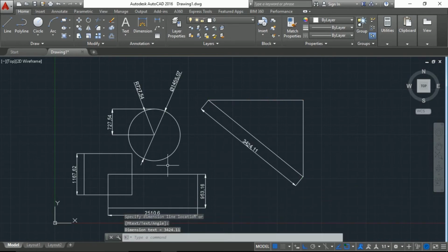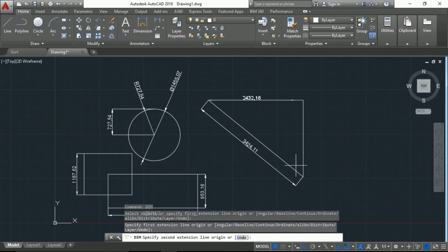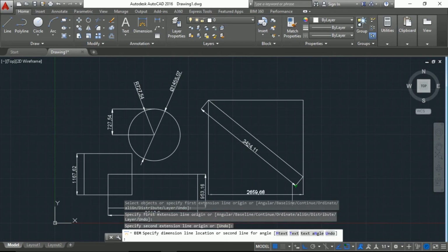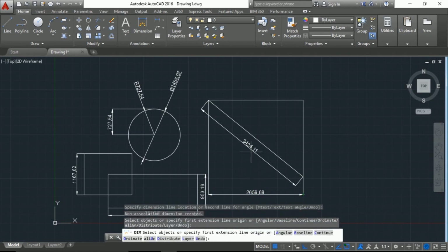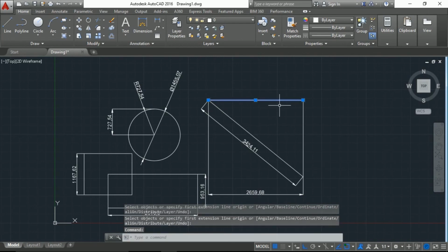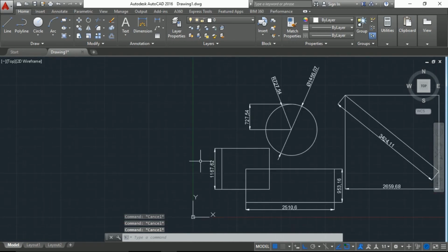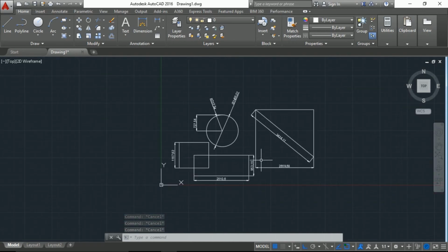Now again, if we just use the dimension, that is DIM, between the same 2 points, the dimension is going in a horizontal way, which means you will never get the correct dimension between these 2 points. Now this dimension which we have got is of the horizontal line which I had drawn above. So you have to be careful for which type of dimension you are using.